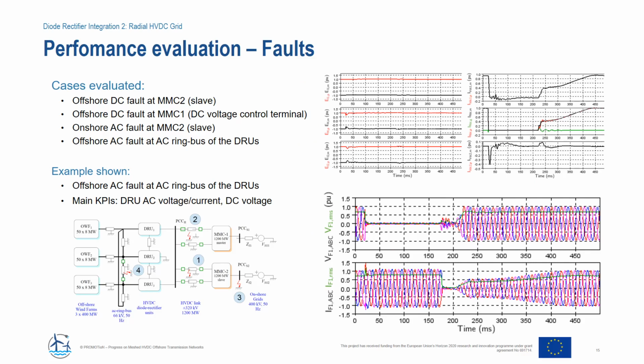Once normal operation was shown with the considered controllers, a large number of faults have been studied, both in the AC and the DC grids. One of the main aims has been to minimize the number of DC circuit breakers required for safe system operation. Depending on the allowable fault recovery time, it is possible to operate the system without DC circuit breakers.